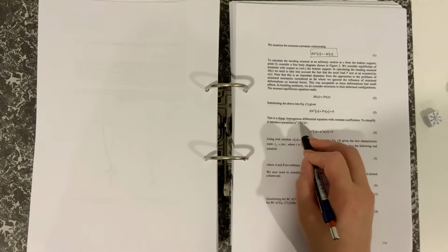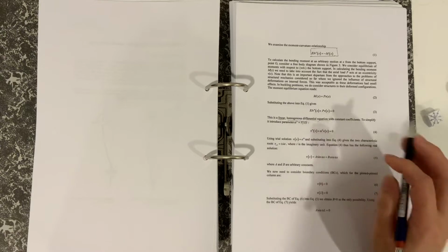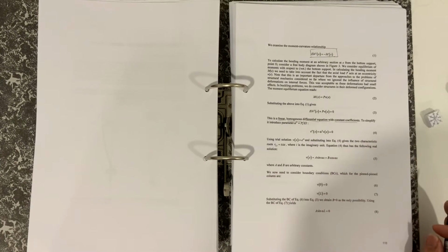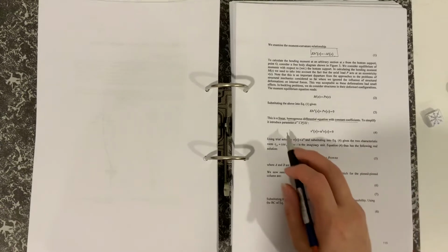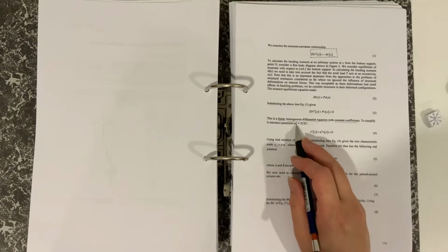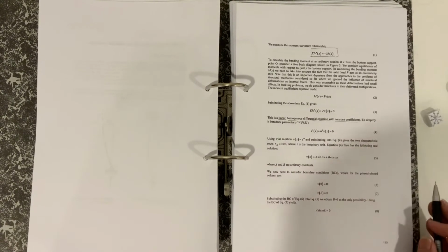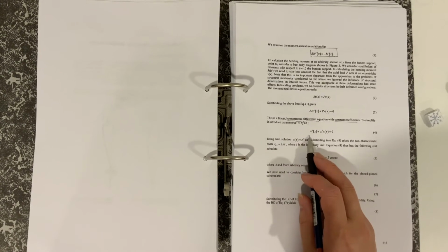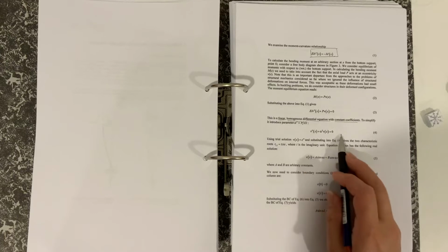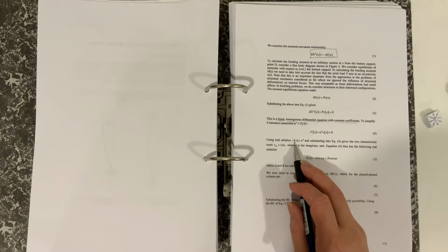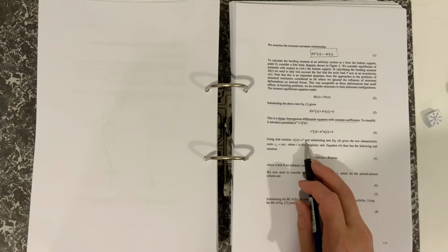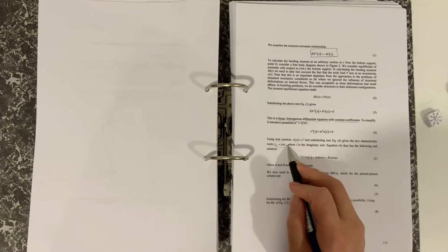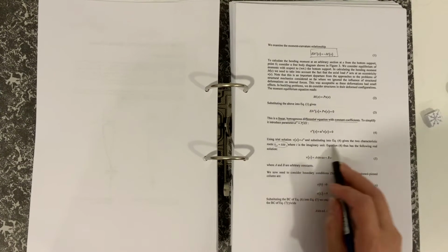So if we substitute that relationship back into equation 1, we get this expression here, which is a linear homogeneous differential equation, which I'm sure you've covered in year 1, and that's got constant coefficients. To simplify it, introduce alpha squared equals P over EI as a parameter, and then you get that expression there. And then using the trial solution V of x equals e to the Rx and substituting back into there, we get 2 roots, one of which is imaginary.